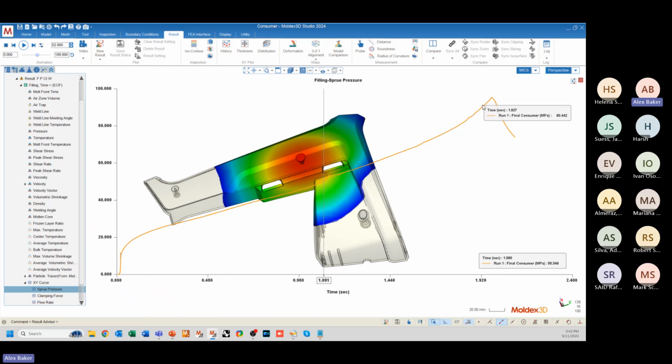And in most cases, that amplitude will increase above the expected maximum pressure, which first of all will create a very impulsive force onto the machine, which can hurt your machine long term. But second of all, it will increase the pressure requirement needed to make this part, which if that impulsive pressure spike goes over or goes close to the machine maximum, that's really where you can start doing damage, especially over a large number of cycles.